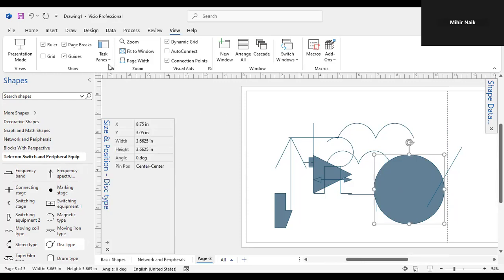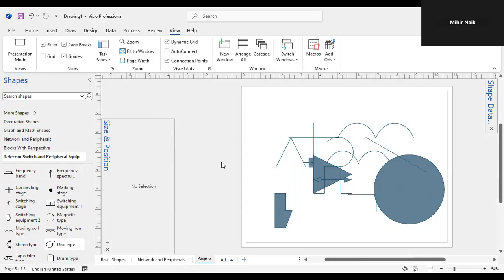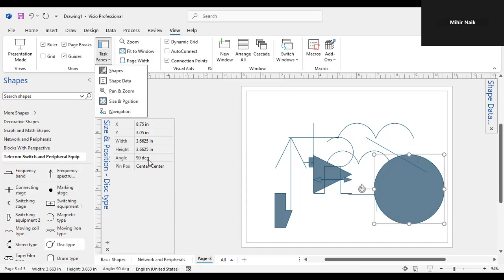So you want to give the position of it, angle 90 degrees. See, this thing has turned from right to left. So the direction has changed. Direction of what? This line, can you see this? Yeah, but why is that line directed that way? When I went to the task panel, I gave the angle as 90 degrees. It was 0 degrees.